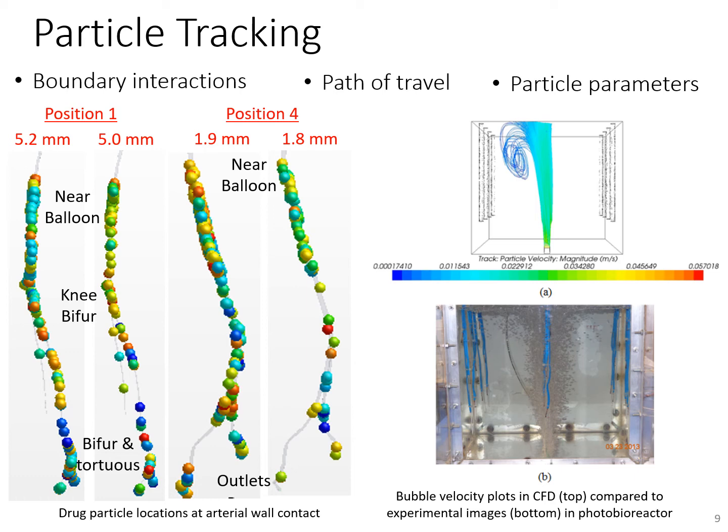The particles were set to escape the simulation if they contacted the top boundary, similar to the bubbles dissipating when they reached the top of the open water column. It was interesting to note how the simulation showed a vast majority of the particles simply continue upward toward the open end of the water column, but a few bubbles tend to recirculate back down into the water column and travel back toward the bubble stream, which is also noted in the tabletop experimental testing.